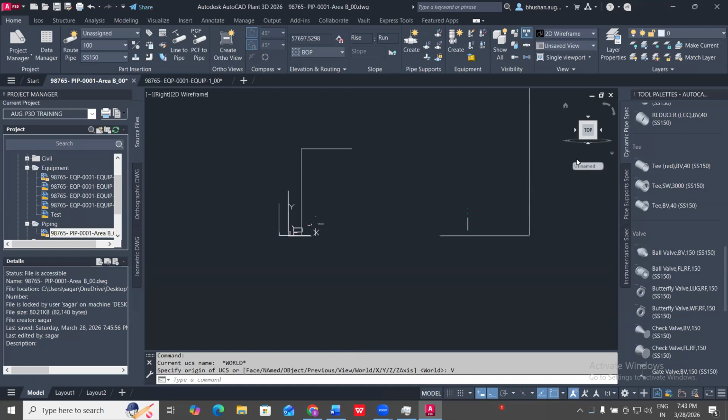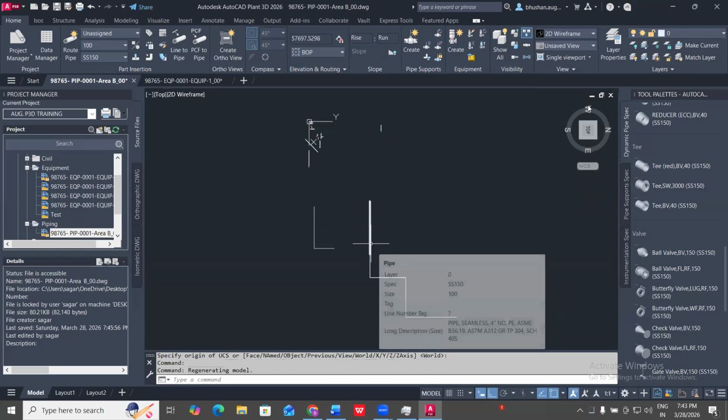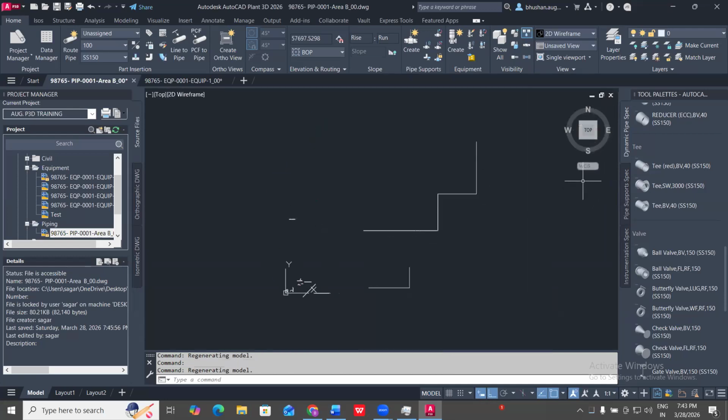Like, it would not show you the Z axis, but when you are finished with this, you need to click on this unnamed option, select WCS, and then change the plane. Why am I saying this? I will show you again.